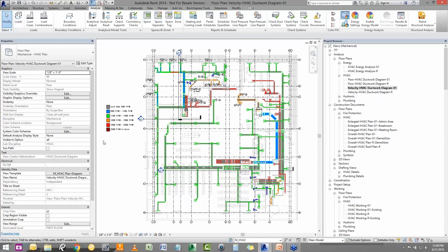like the workflow I talked about where we go into the architect's model and turn off their ceilings as room bounding elements, if you do not do that, when you place spaces inside of your model, it's going to stop at the ceiling. And then anything that would be in the plenum space wouldn't be automatically counted because it's not included in the space. However, everything comes with a room calculation point now, so what we can do is adjust that room calculation point to be lower, say significantly lower, 5-6 feet below that VAV unit. Therefore, it would be counted in the space, and it would show up in our space schedules, quantification schedules, and everything else.